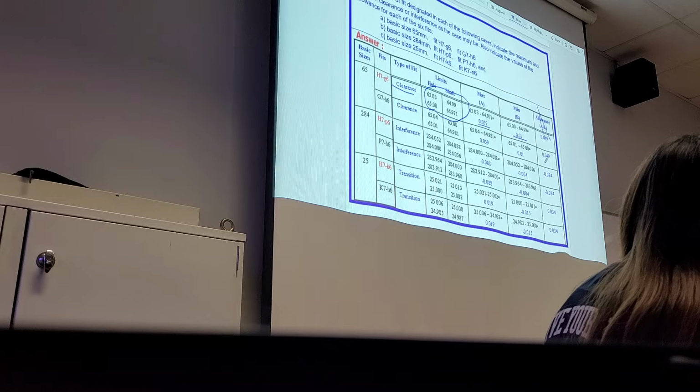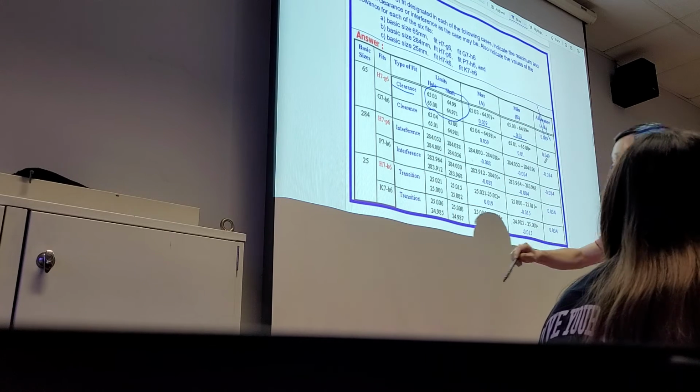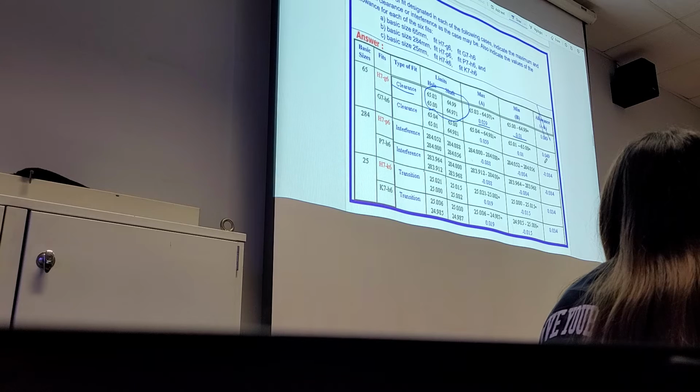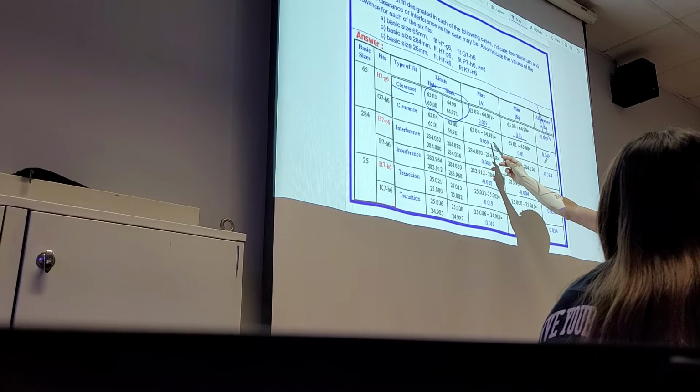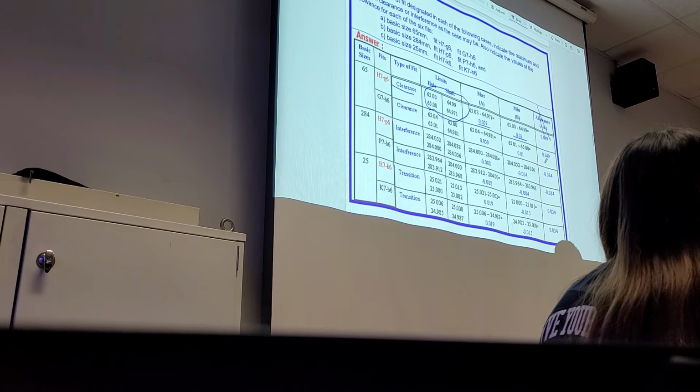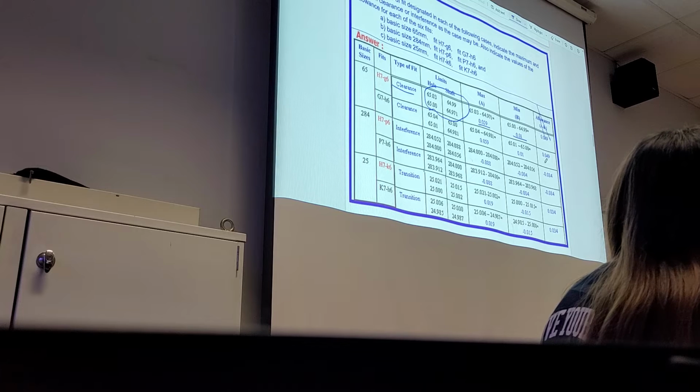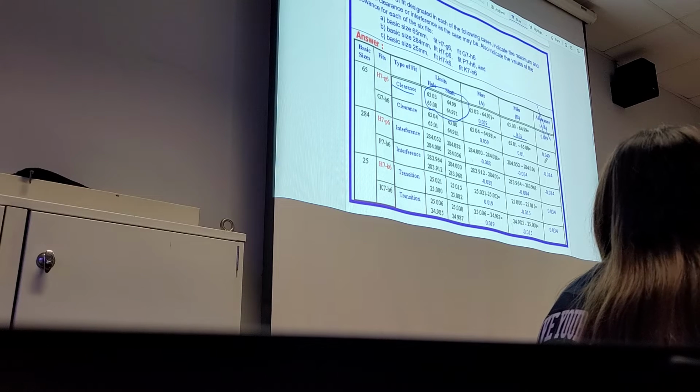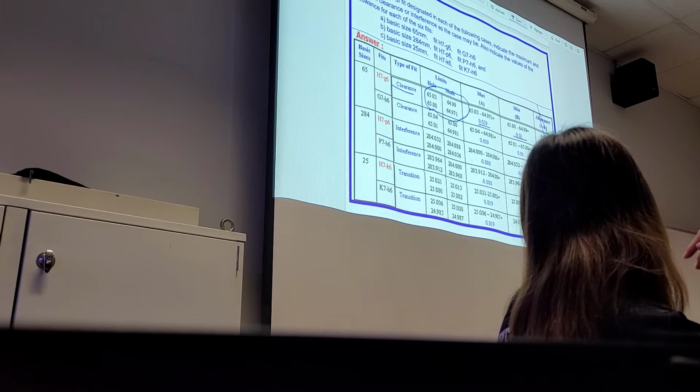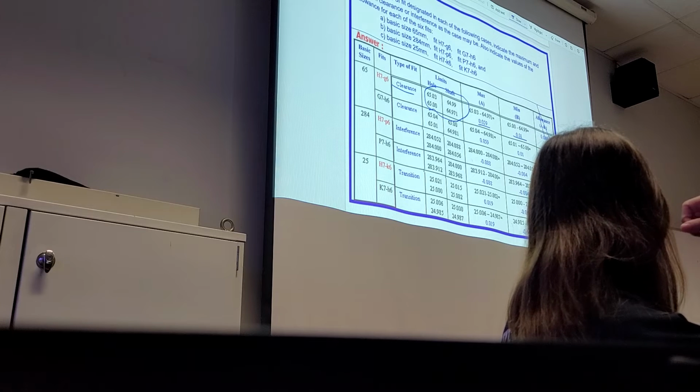And then there's G7 H6. Basically, these two are mirror images. From the table, you get another set of data, and finally you find they are exactly the same, because the maximum and minimum clearance are the same. So although these two specifications look different, they work in exactly the same way. That's what we mean by mirror image: one is the hole basis, one is the shaft basis. You can do the same thing for interference fits and transition fits.